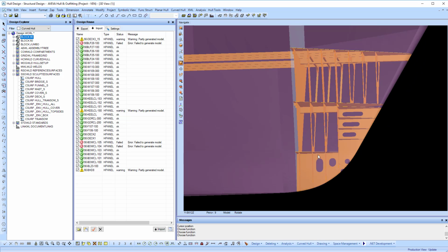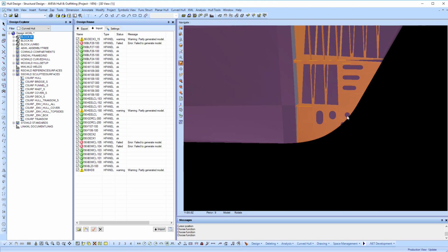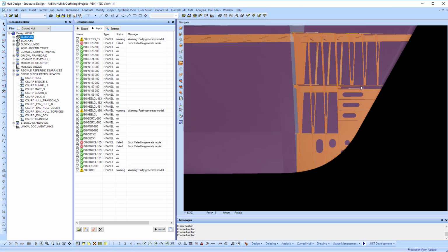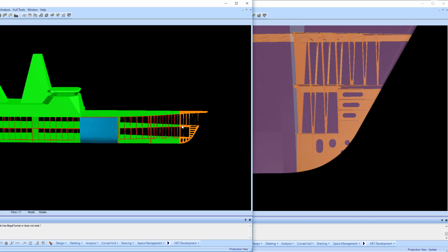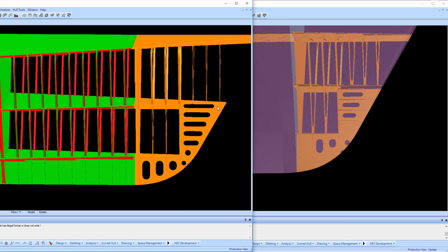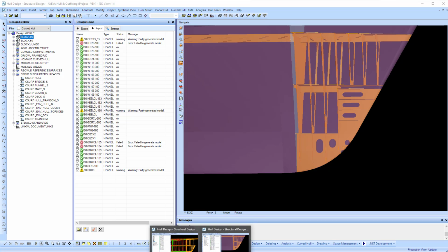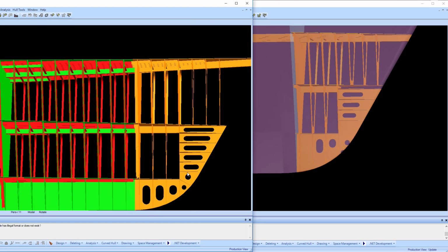We can see that some of the failures are probably due to the fact that we've got some holes falling off the surface, the geometry has changed, and if we start comparing the design, as we will see here, with the original, probably got quite a significant design change. Between decks 1 and 2, we have 6 breastplates, whereas the target design really only fits in 3 plates with a hole. So it's quite a big difference between the two designs, and this illustrates that really what we're doing is transferring the design rules.